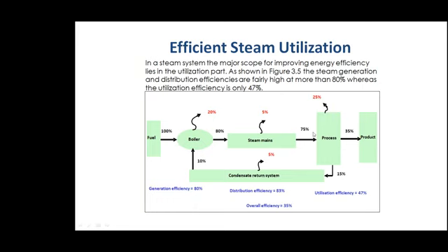And so 75% we are putting, but 28% goes off as losses. So we have considered various losses, those losses go off. And another 15%, the steam condenses, the condensate is coming out. So 15% comes out here in the form of condensate heat, which is normally recovered. So 10% goes back to the boiler and 5% is the loss, the radiation convection loss as it goes through the pipelines.